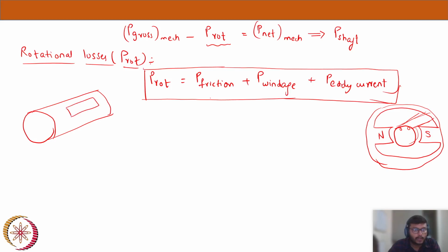Let's say you take any closed path; it will be under the influence of the magnets, which will be like this. This is the small closed path we took, so eddy current will flow inside the body. That current will cause heating, and that contributes to the eddy current loss. So instead of taking this entire solid body, people make layers. That's what we call laminations.